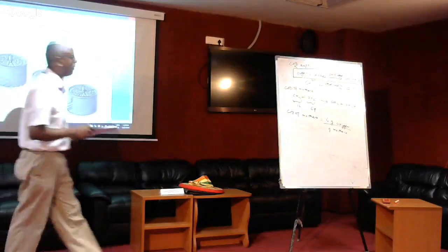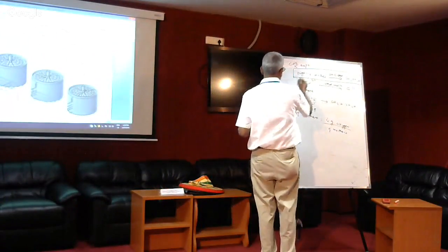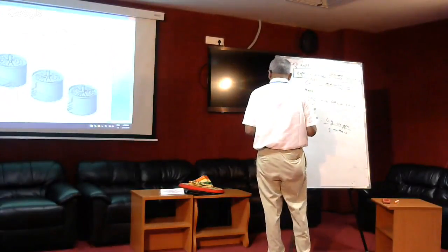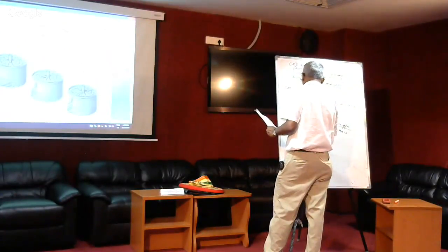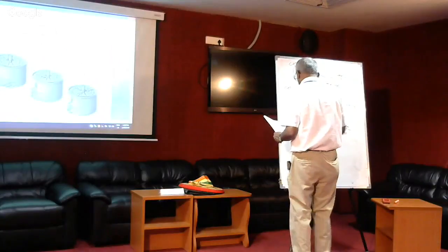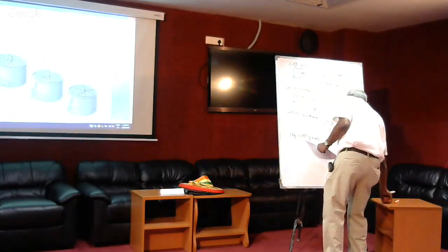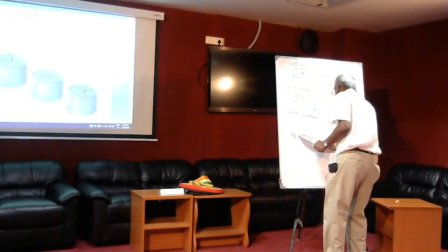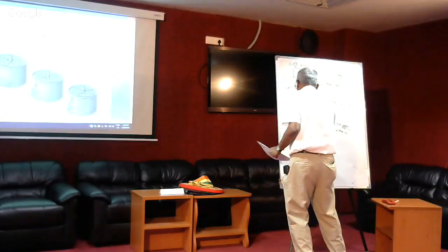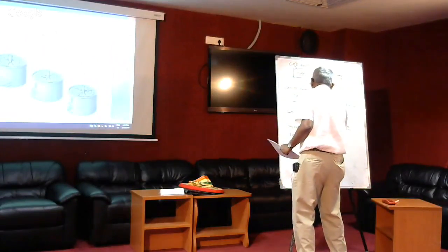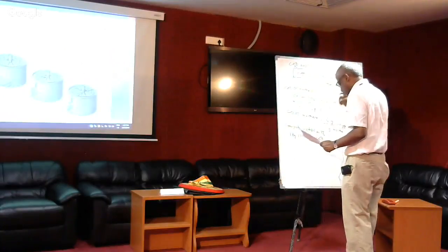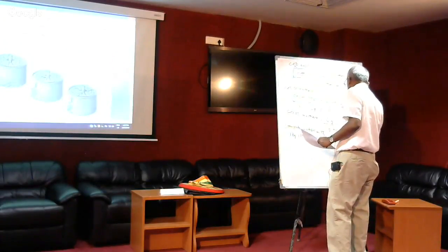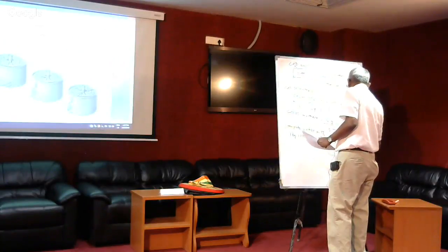And so now we can correlate this. Excuse me. 1 kilogram or 1,000 grams of COD, complete metabolism of 1,000 grams of COD will produce how many grams of methane?